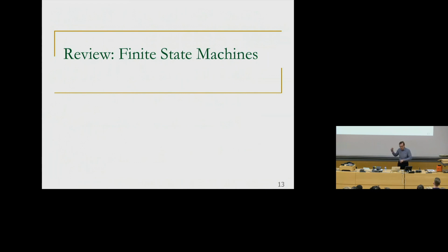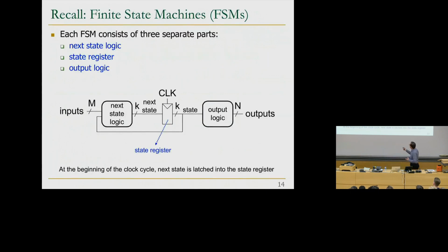Delay is very important. But for that, you need a different kind of construct, which is the D flip-flop, right? Flip-flop was the state element we introduced. That's not level sensitive, that's sensitive to the triggering of the edge. Later, we will see the Verilog implementation of the flip-flop in this lecture. And that's how you build finite state machines. And you use flip-flops for the state registers.